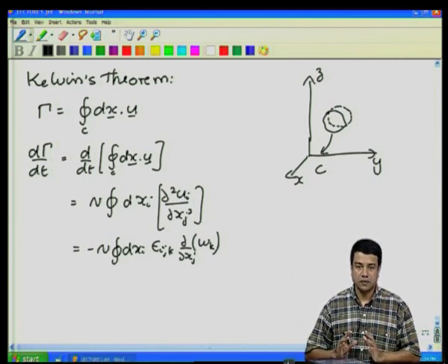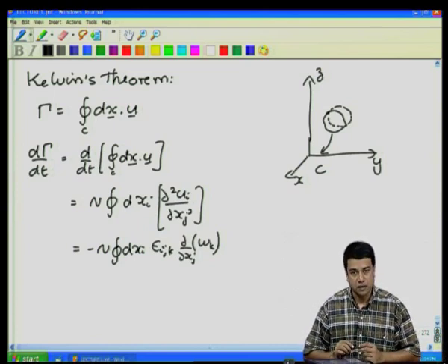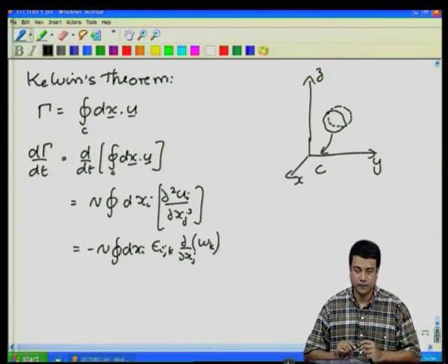And that is the reason why we could talk about potential flows, because we know that if the flow initially did not have vorticity, it has to continue to not have vorticity internally, right. You cannot generate vorticity within the flow. So, where then can vorticity be generated?